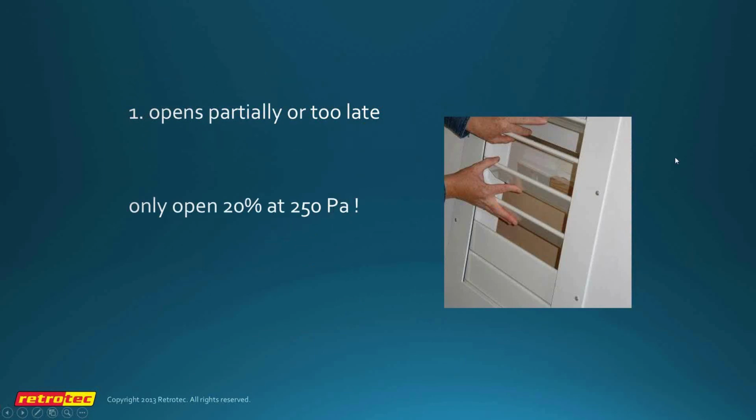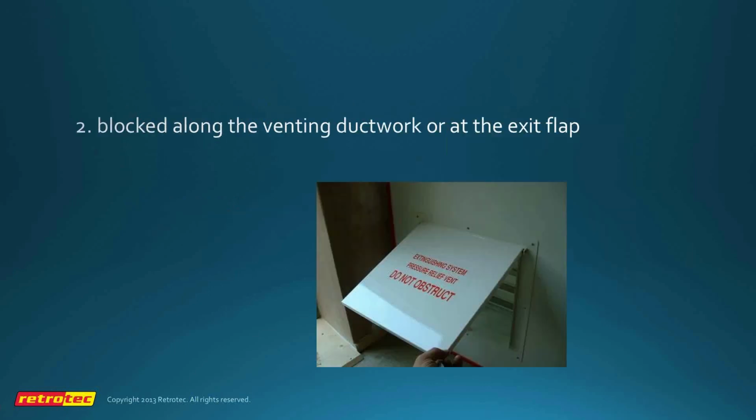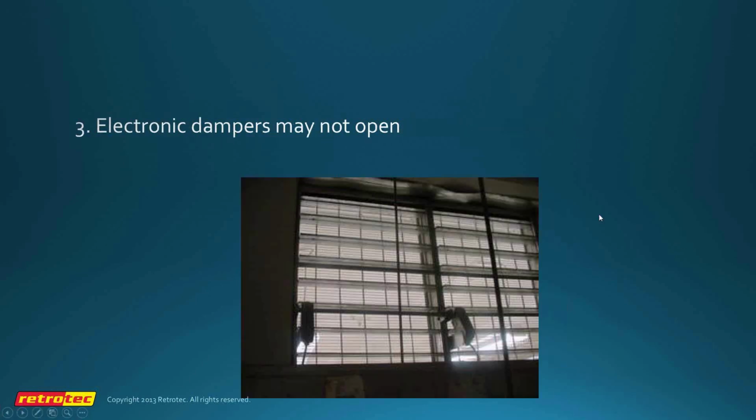A test of the vent in a box or even in the room will show that very quickly. Or the vent can be blocked. So we may have a vent that has tons of area, but it's blocked. It has a rain flap or something in front of it, and it's obstructed in some way. That's why the venting path needs to be measured on a regular basis.